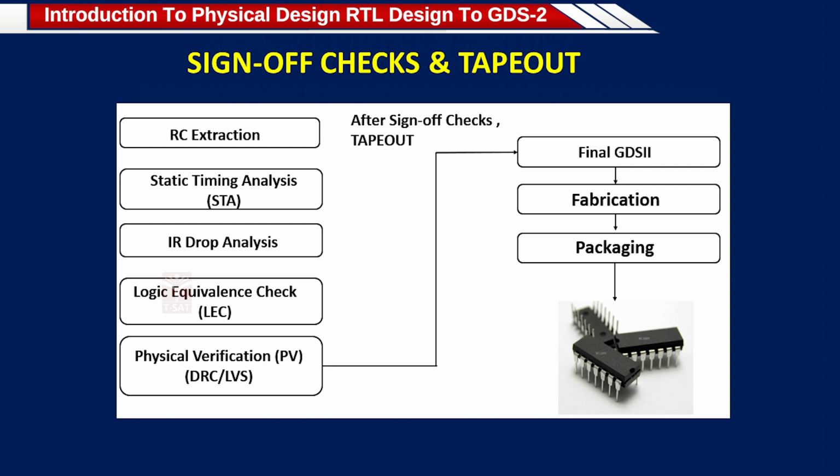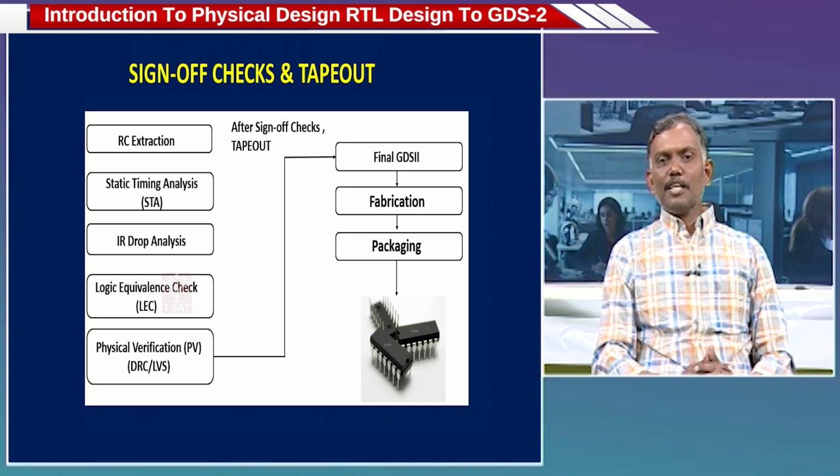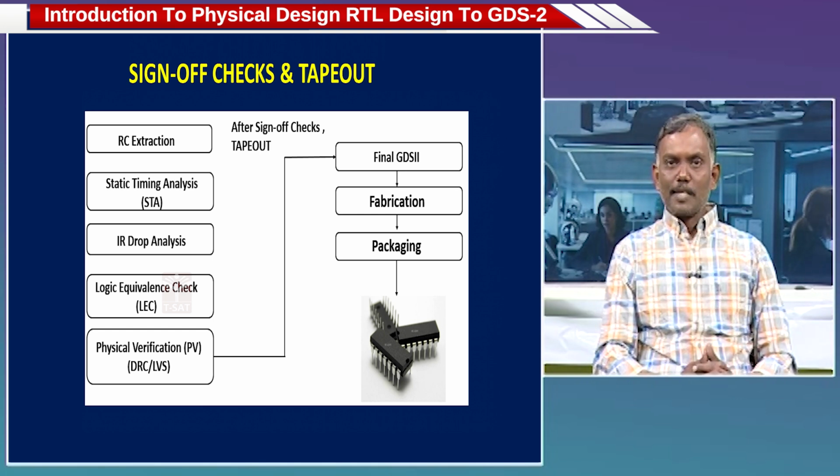Next is static timing analysis, STA. In logic synthesis, we did STA. In place and route, we did STA. But still, that is not sufficient. We should run one more round of static timing analysis using the sign-off tools. That is sign-off STA.